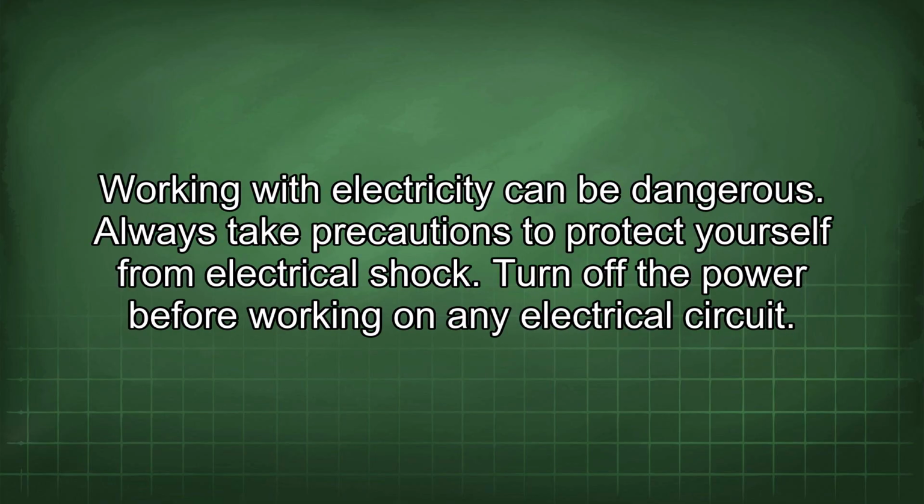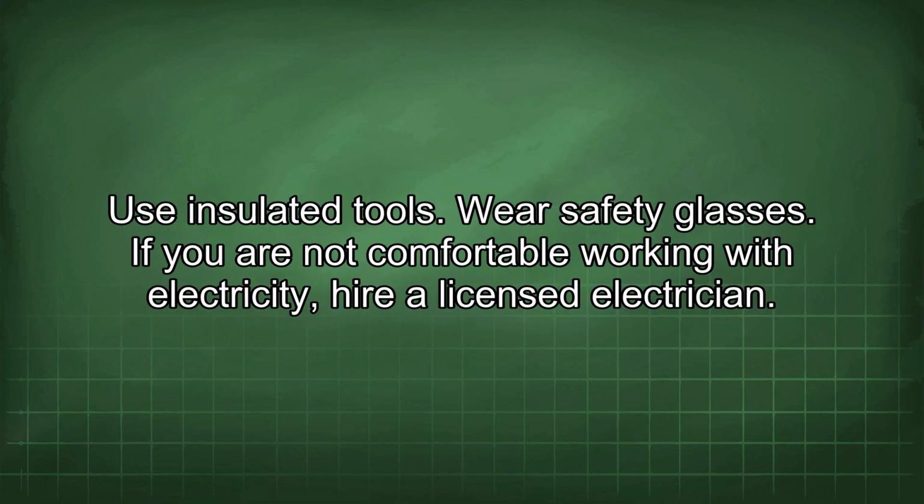Working with electricity can be dangerous. Always take precautions to protect yourself from electrical shock. Turn off the power before working on any electrical circuit. Use insulated tools. Wear safety glasses. If you are not comfortable working with electricity, hire a licensed electrician.